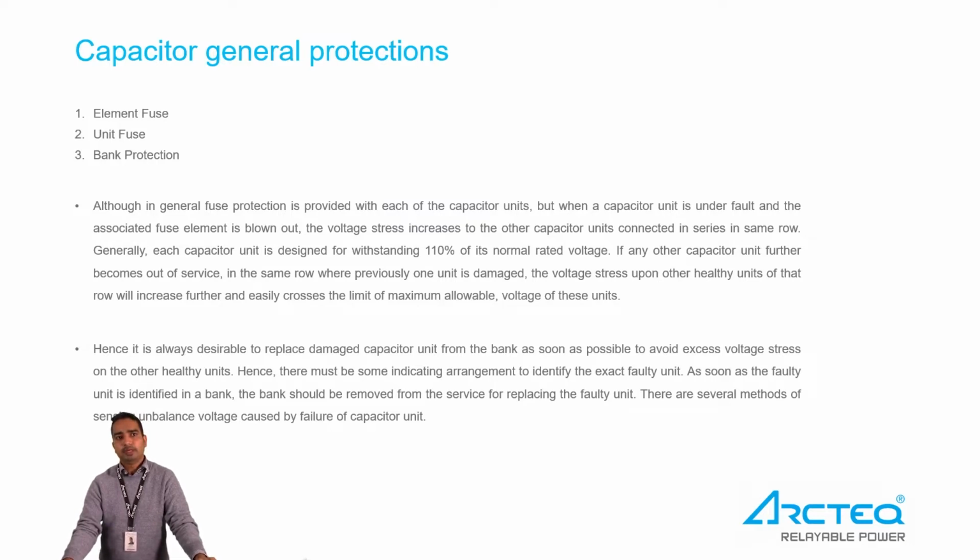The problem appears when multiple fuses start to blow out and multiple small capacitor components go out from the bank. Then, for example, if 3 or 4 capacitors are blown out from the same string, there will be a voltage stress on that particular string.